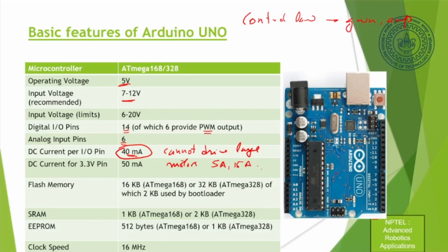So it can't drive that. You need an amplifier or a power supply from outside. That will come in here, so that's your external power. It is basically required for amplifying whatever signal is coming from the microcontroller, which then goes on to drive the motor.